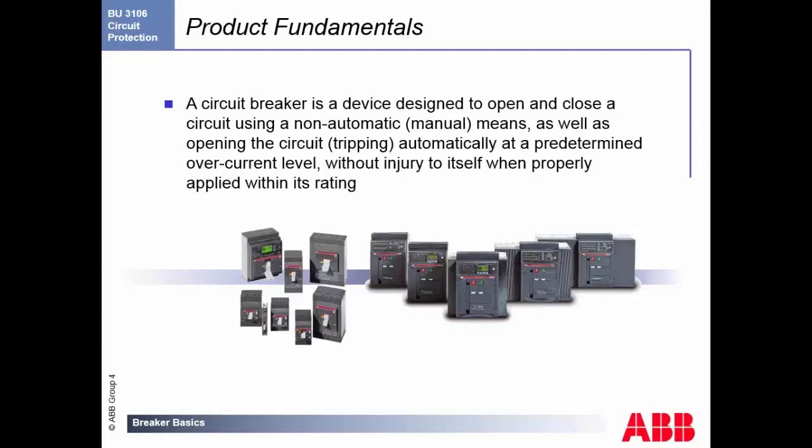It also has the ability to trip or automatically open the circuit based on overcurrent levels without injury of anybody being around. So if you have any kind of short or an overload, and we'll talk about the different types of faults that you may see down line, this breaker is there for safety for both the person and the equipment, where it will open up and make sure that all power is disconnected and service can be done down the line from the breaker.